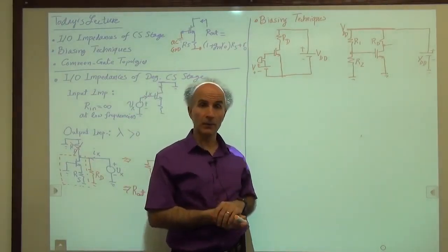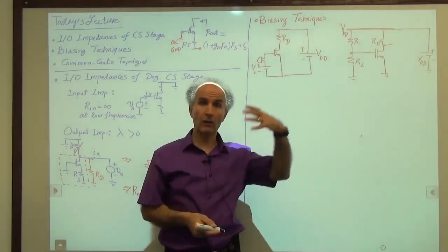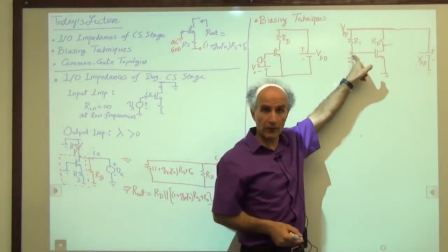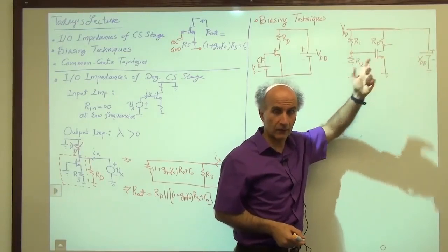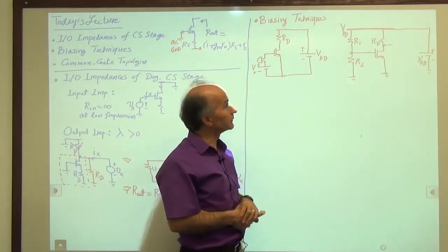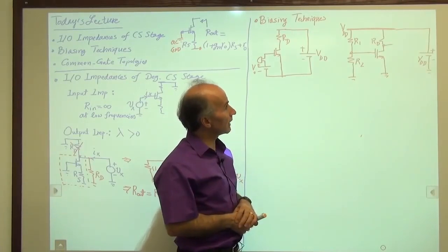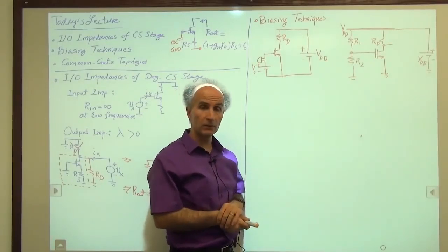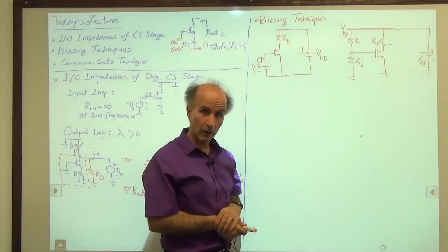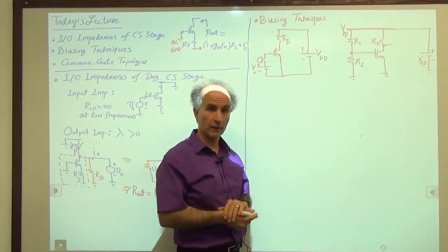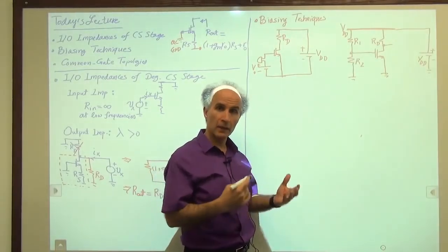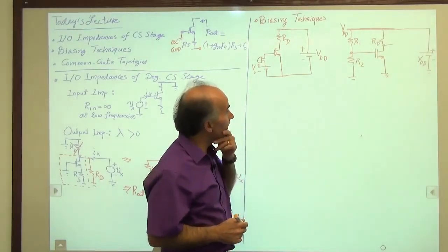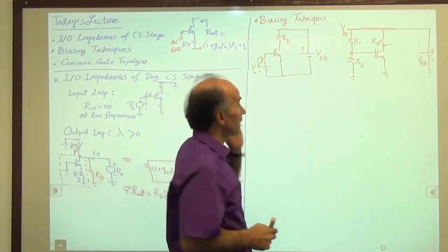So that seems like a simple approach that we can repeat for all of the stages in the circuit. Every stage would have its own resistive divider and would provide some amount of voltage necessary for the gate of this device. So we can do that. All right, that's good. That's a very basic circuit for biasing. In fact, this is not very commonly used in integrated circuits where we have many of these MOSFETs and many of these stages. But at least for now, to get our feet wet and familiarize ourselves, that's fine.